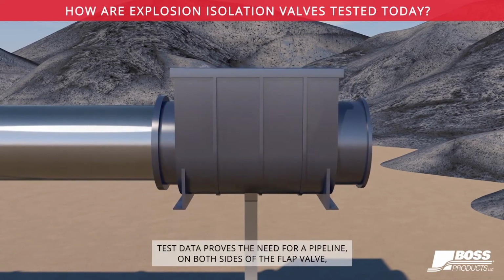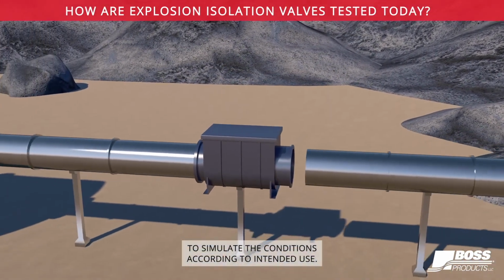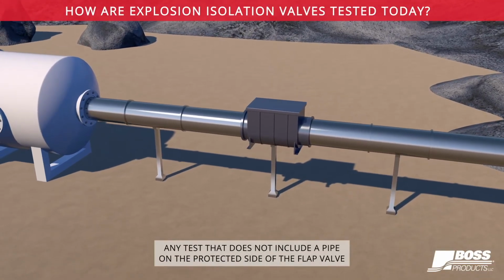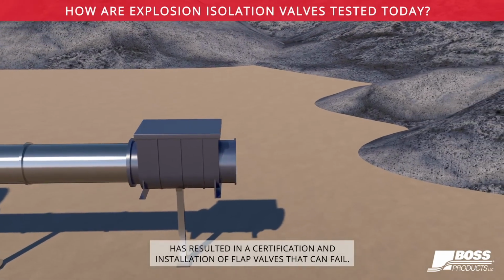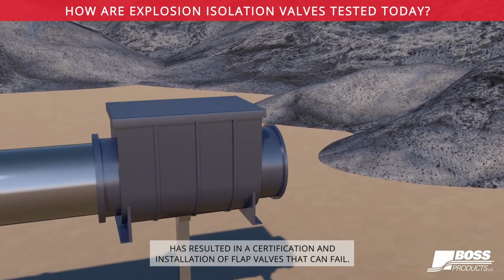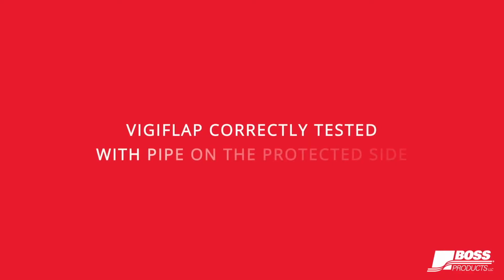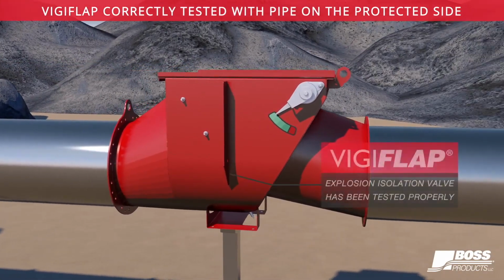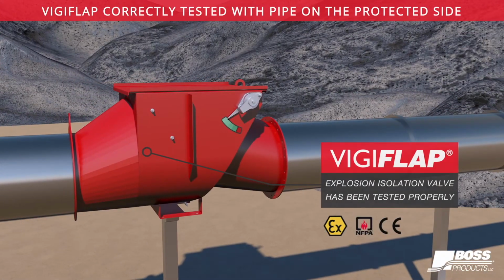Test data proves the need for a pipeline on both sides of the flap valve to simulate the conditions according to intended use. Any test that does not include a pipe on the protected side of the flap valve has resulted in a certification and installation of flap valves that can fail. So how we test our VigiFlaps is we put pipe on both sides, because as this will explain, there's going to be pressure on both sides when an explosion happens.